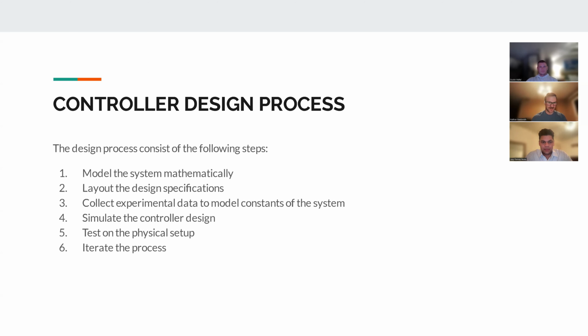We then simulated the controller design and tested that on a physical setup. We experimented with a proportional integral controller, a proportional derivative controller, and a proportional integral derivative controller. And through all that process, we used MATLAB and root locus to find our final transfer function.